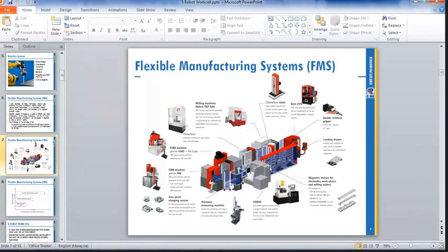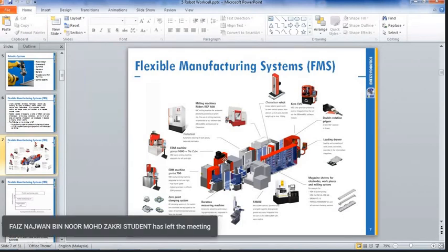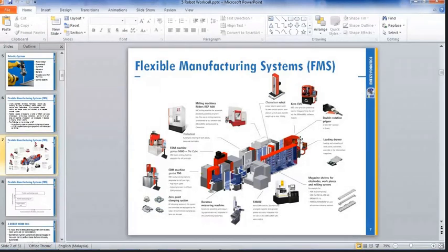What about other companies in industrial or semiconductor? If you go into the industrial semiconductor sector, you can see a lot of this type of FMS system. For example, if you do an internship in semiconductor, they have a wire bonding machine that puts a gold or aluminium wire on the semiconductor chip, or you can see a die attach process. They insert the chip on the PCB, but their system will be a straight line like this, and your product will be transferred using a conveyor belt.